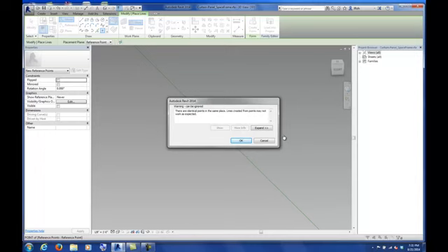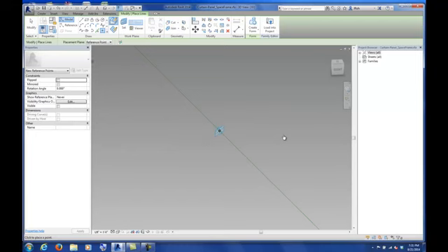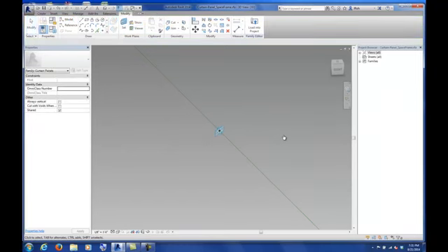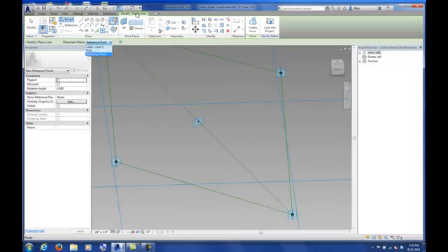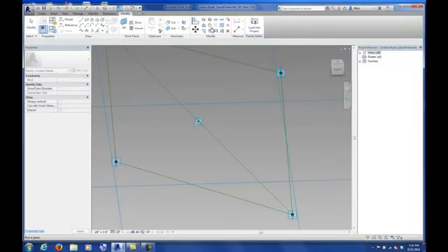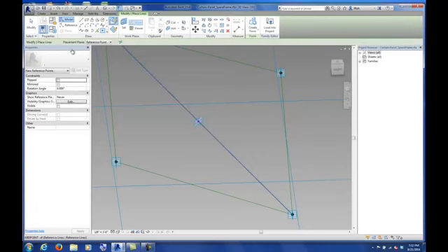And you'll get this error message that says, by the way, there's identical points in the same space. That's okay. I'm going to do that a couple times just so everybody gets it. I wish these planes would get bigger as you zoom in, but they never do. It's kind of unfortunate. Again, what I'm doing is I'm clicking on point, placement plane, selecting pick. I'm hovering over this point right here. I'm hitting the tab button one time, and it should select the horizontal. I left click, then I left click again while I'm snapping to the middle of that particular point.